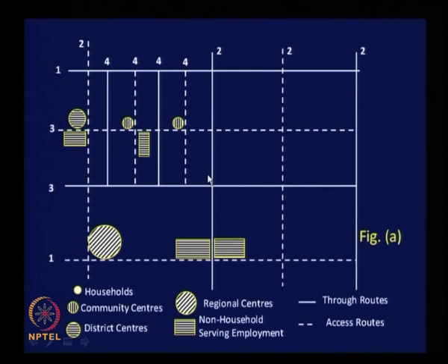Interestingly, you can find that type 4 also has 2 categories. They have carried the emphasis on speed even to type 4 category of roads, which are really basically intended for integration of land with road. They wanted to have even type 4 through routes, emphasis on speed only, as well as type 4 roads with emphasis on access, land access. And again you can see the category alternately through and access roads side by side in all the types.